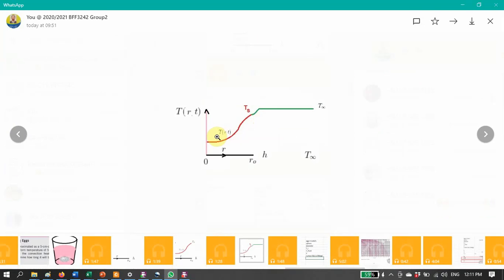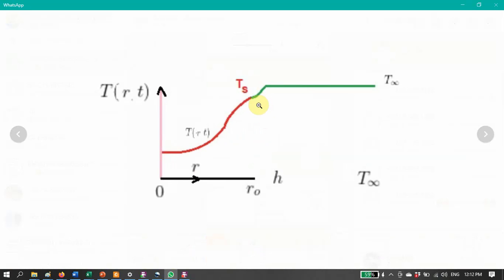So this is another plot, and after I made some changes there, I also added the temperature distribution inside the fluid, right? After we have the surface temperature, there will be some temperature profile inside the thermal boundary layers, and then we're going to have a uniform fluid temperature away from these thermal boundary layers. So here I show you both the temperature distribution inside the solid, inside the thermal boundary layer, and inside